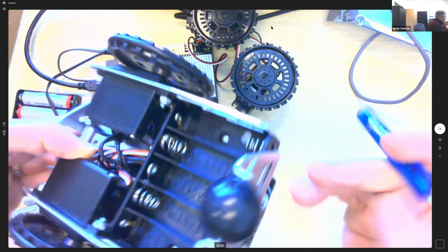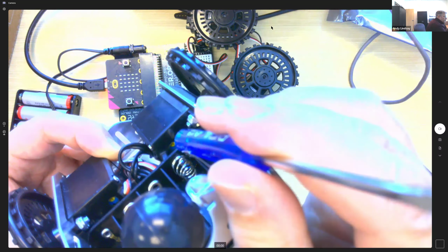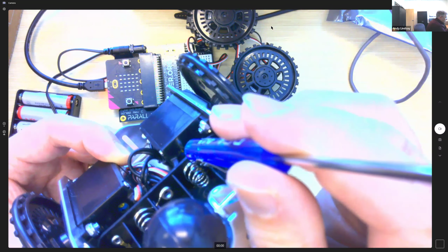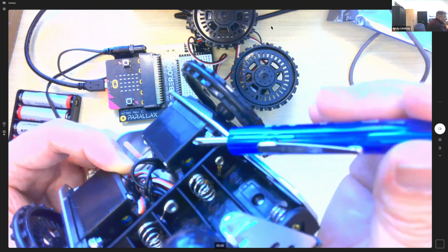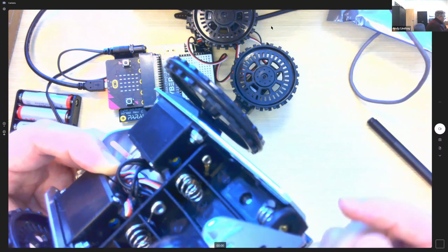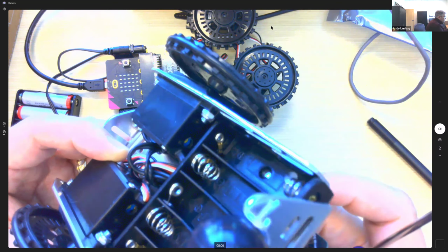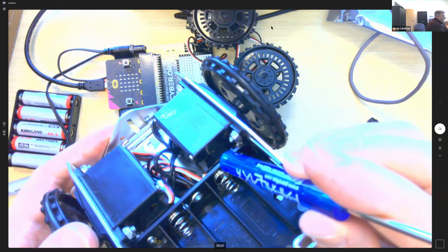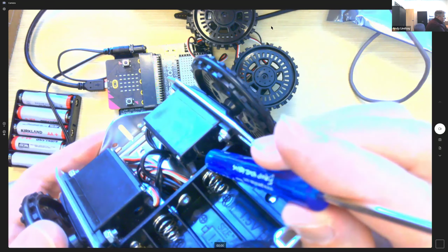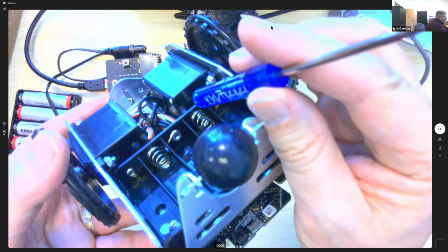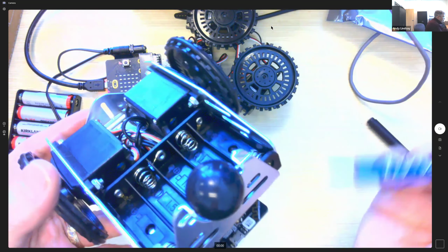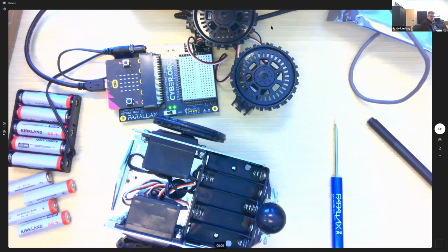Once you take the battery pack out, then you'll be able to get the screwdriver in right there where the hole is. Then you'll put the batteries back in, and you'll have it running and the wheels will be turning. And then you can go in and adjust it. Don't try to do it with the battery pack in like this, but once the battery pack comes out, you'll be at an okay angle to get in there and adjust it.